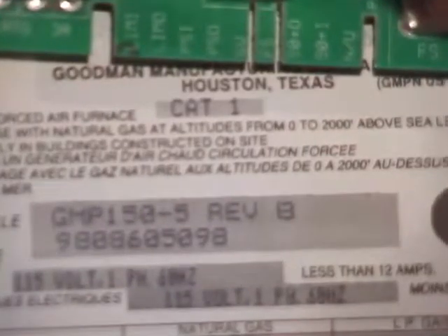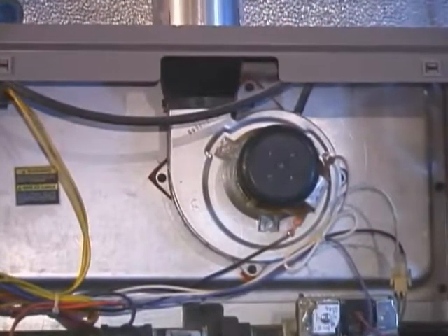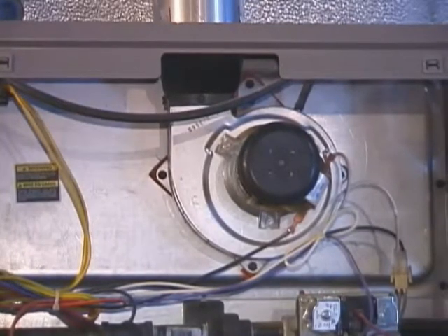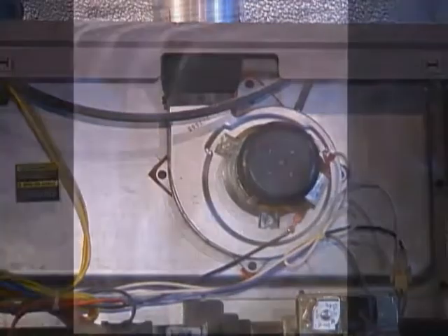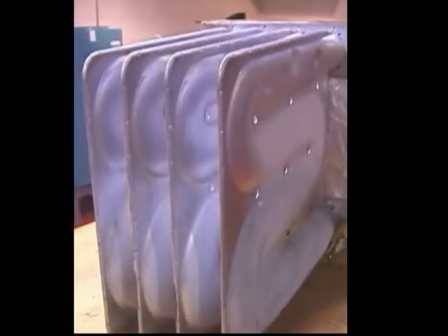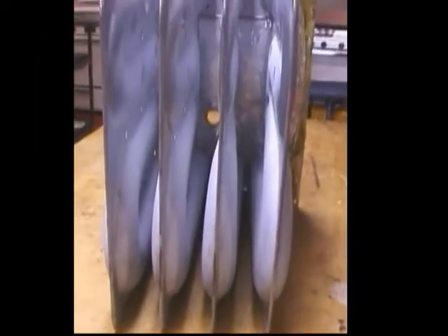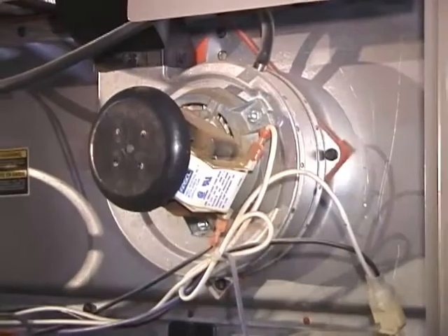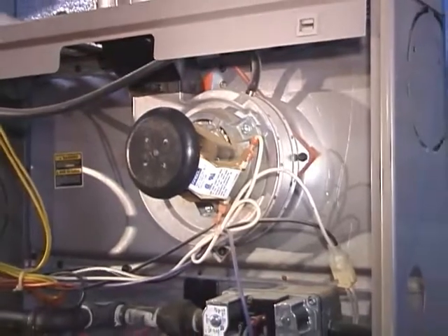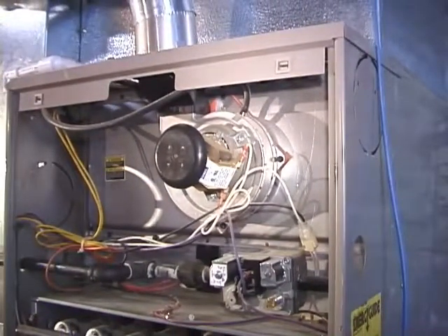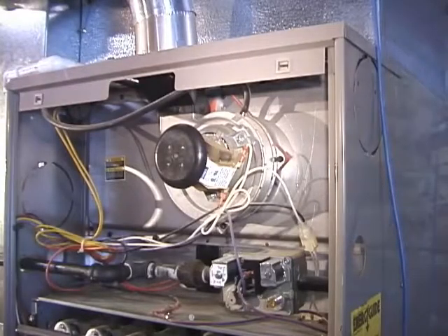It is a common misconception that the inducer fan in these appliances is there to force the gases up the vertical vent. In fact, its role is solely to pull the gases through the furnace heat exchanger, which has more resistance than the open heat exchangers common to older style furnaces. Once the fan has pulled the gases through the furnace, it essentially dumps them at the base of the vent where the draft created by the heat of the gases is expected to take over.